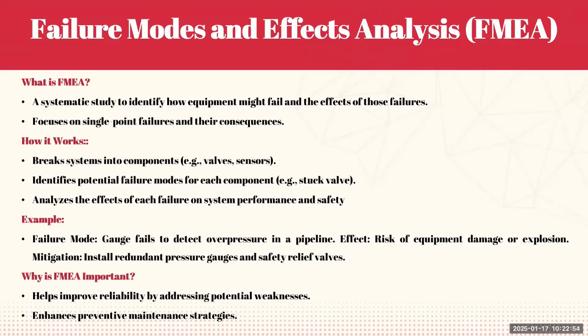So if we have only one and that one could fail, then we need to install separate ones that can help us to avoid this issue. FMEA is important because it helps improve reliability by addressing potential weaknesses, and it also enhances preventive maintenance strategies.